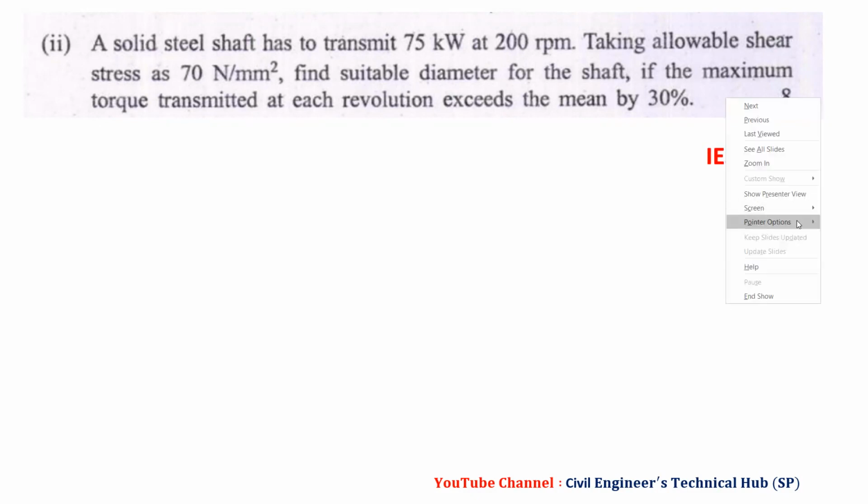This question was asked in 2019 for Indian Engineering Services, that is IES. In simple terms, we know power. So knowing power, we can find T, and knowing T and shear stress, we can find the diameter. So we have to use the first formula.